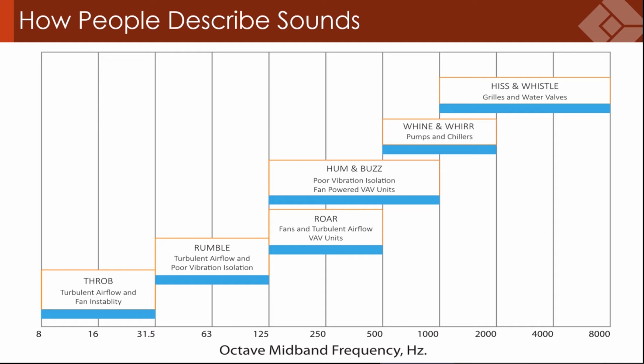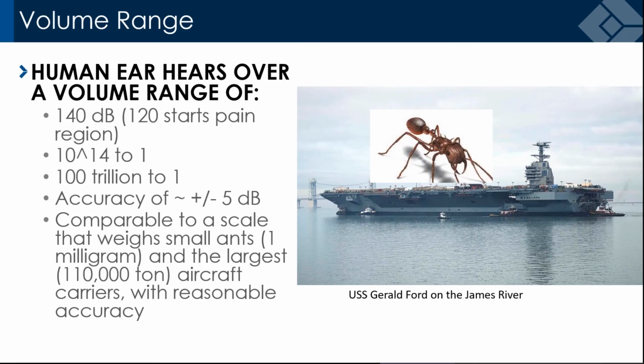When you hear the word rumble, you're thinking this is probably going to be coming from either the main fan or a refrigerant compressor.